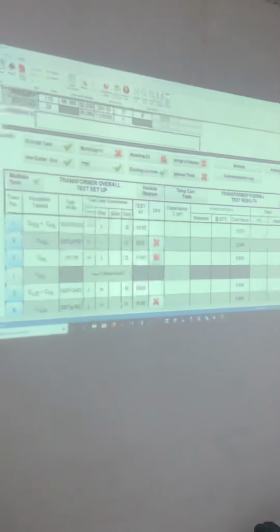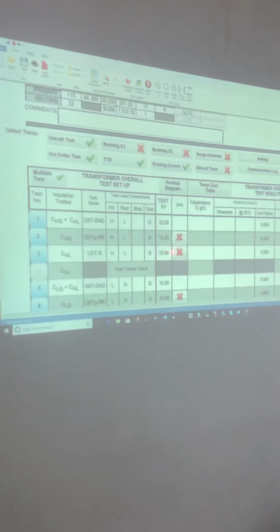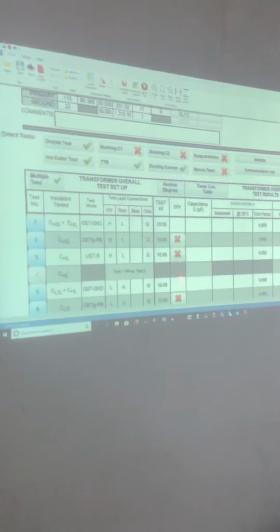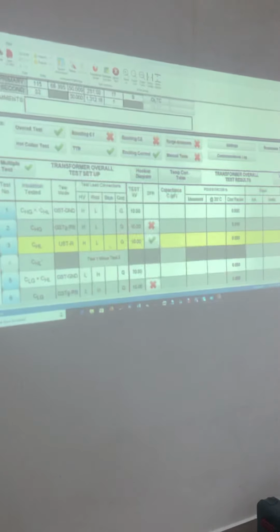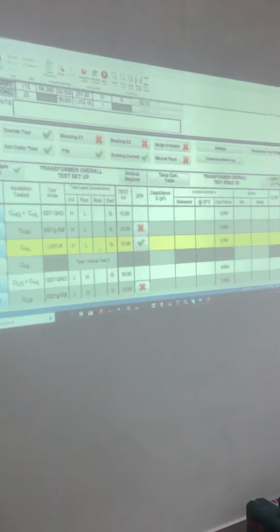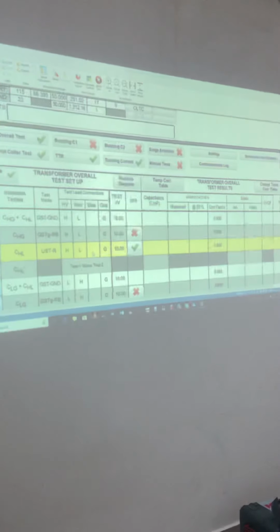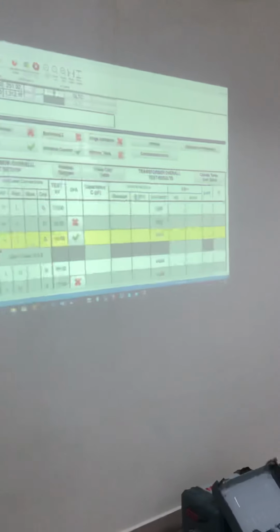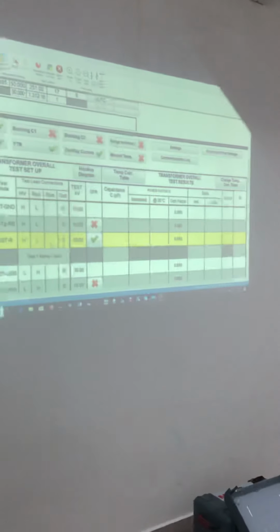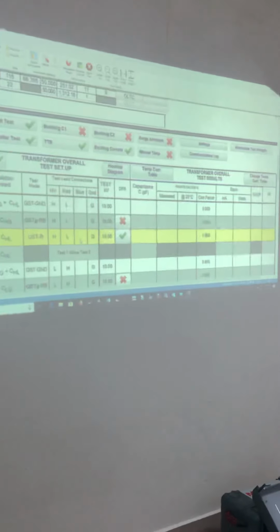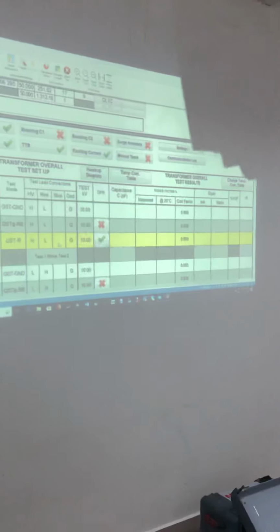And what we are going to do is enable this DFR for CHL. So if you click on that there, what this is going to do is test this from 1 to 470 hertz. And if you remember what I was discussing previously, when you are looking at power factor, so this is PF or DF, and this is frequency. Let's say this is hertz.